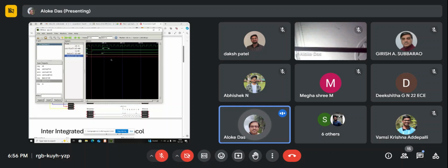Most possible ways of using your hardware, you have to cover in a test bench. If it becomes very big, then write 3, 4, 5 test benches, compile them, simulate, and see the simulation result in GTKWave in waveform form. So that's how you can do the verification very well.